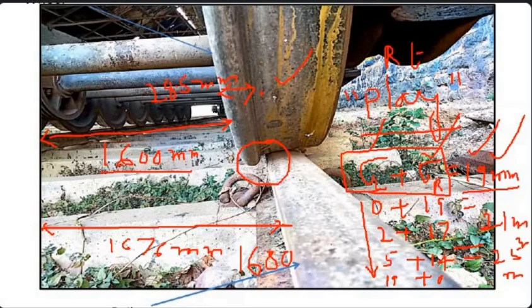It may vary because of the flange thickness reduction. And suppose instead of maintaining 1600 mm, you are maintaining say 1599 as the wheel gauge, for example. So here 1 mm extra is there. That 1 mm will be added here. So this play will change based on these parameters. That means if you are not maintaining 1600 wheel gauge, the play will change. Suppose the track persons are not maintaining 1676, they are maintaining more. Then also play will change.